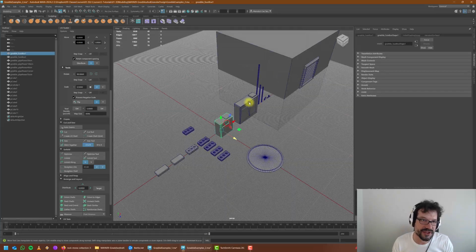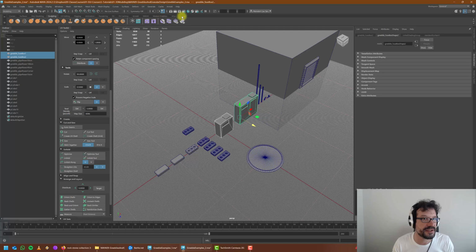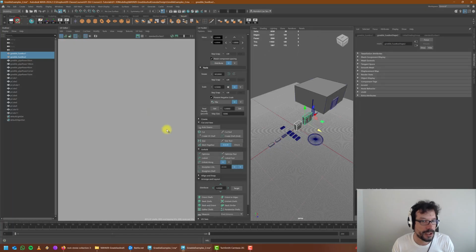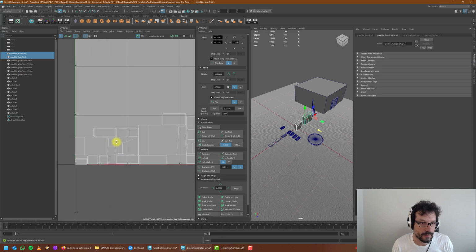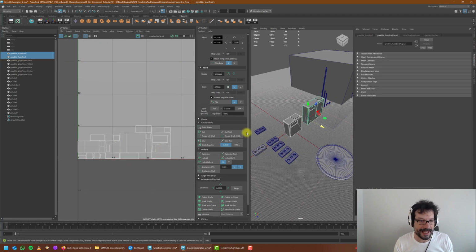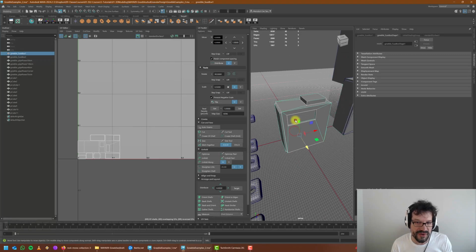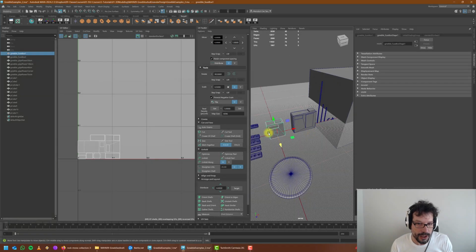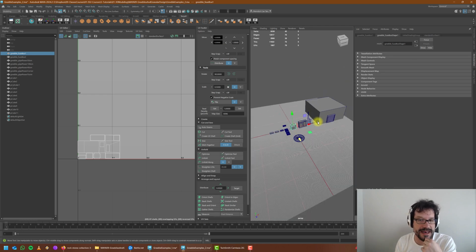And when it comes to texturing, always be aware of the situation. Okay, it's easier to do things earlier on the modeling stage than later, because once you UV unwrap this thing, when you create variations out of it, it will be easier to unwrap or modify the UV maps of other ones than do it from scratch. So keep that in mind always.